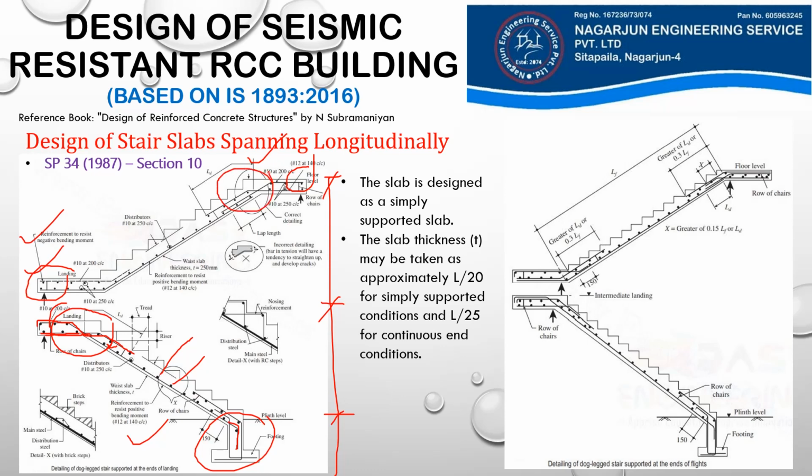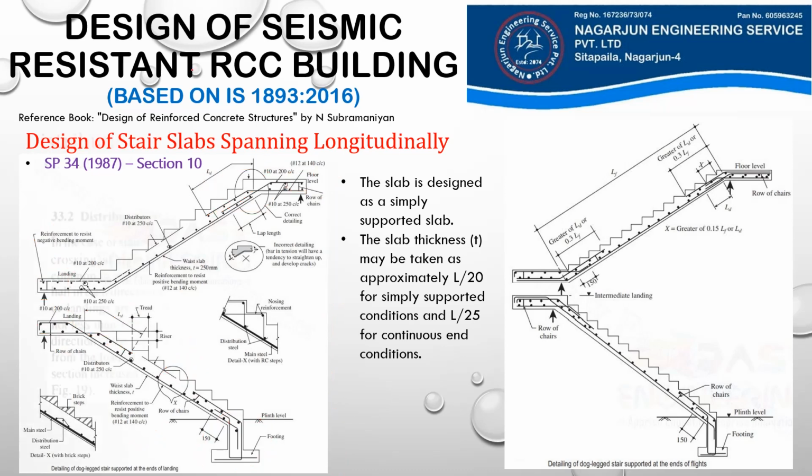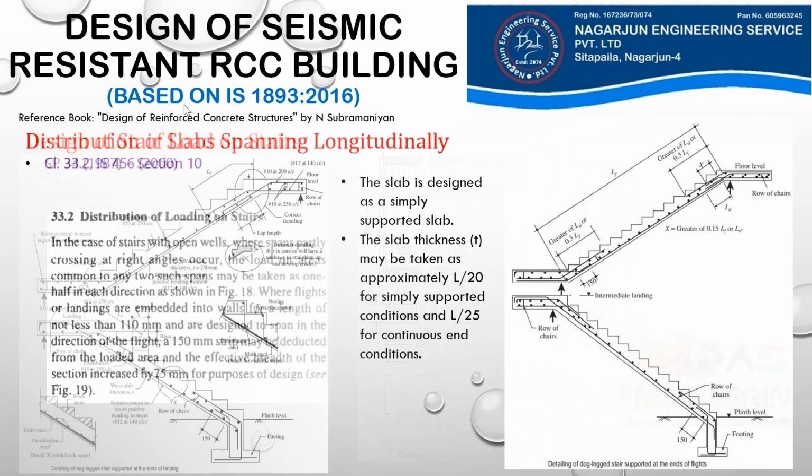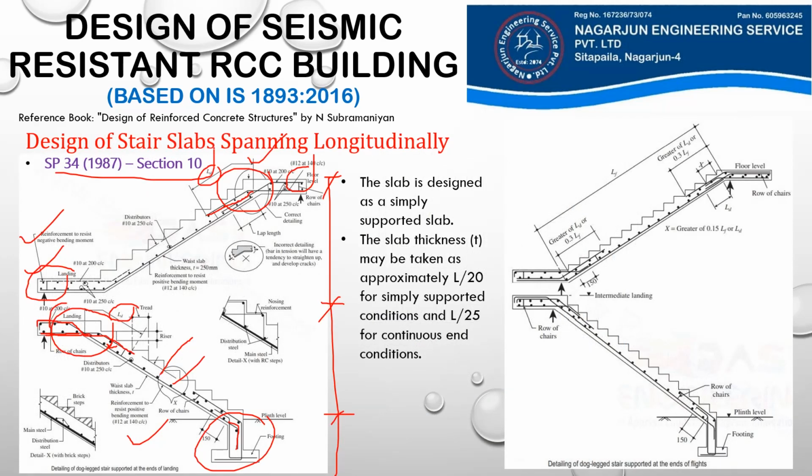There is a scissor type arrangement here, and the length of these reinforcements here or here should be at least equal to the development length of the reinforcement. You can get the general detailing of these staircases anywhere, and you can also follow SP 34 section 10, which includes provisions for detailing of staircases, and you can study this detailing pattern in detail there also, if the diagram is not much clearer or visible to you here.